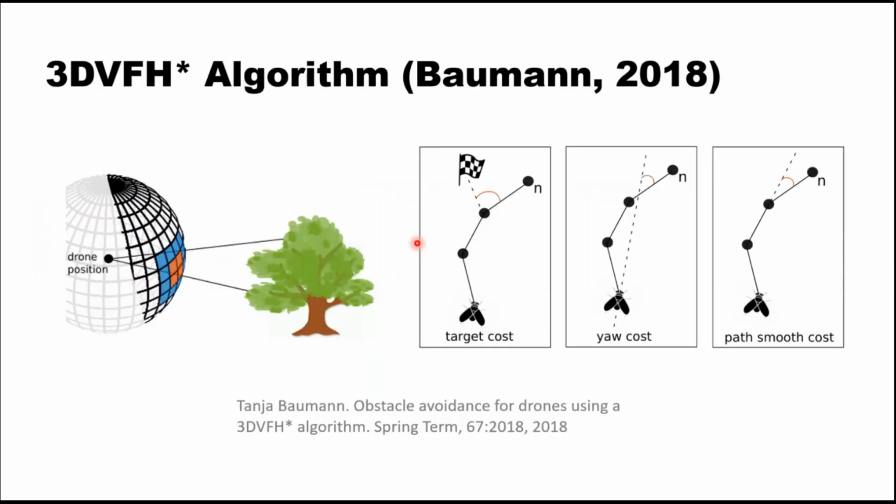And from that, the algorithm 3D vector field histogram converts this 2D picture first into a 3D point cloud, then the 3D point cloud is converted to a 2D histogram. That allows basically each voxel in the space to contain one point from the 3D point cloud. And where there are obstacles, that means this path is infeasible, along with some padding to maintain safety.